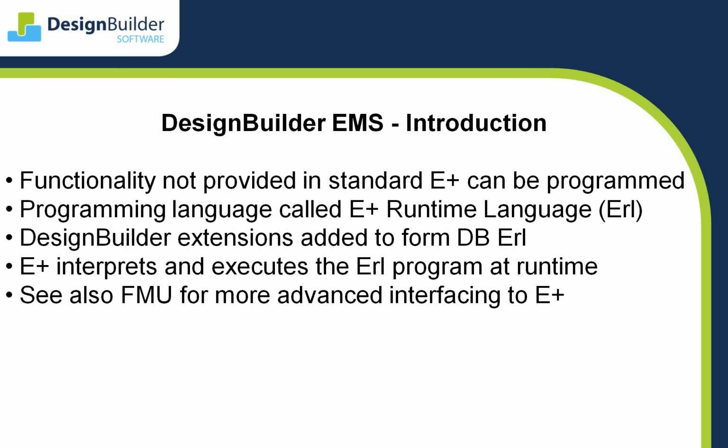The entire EMS program is contained within the IDF file generated by DesignBuilder, enabling you to run your simulations locally or on remote servers. EnergyPlus provides an inbuilt language called ERL, and DesignBuilder provides some significant extensions. These allow a single piece of EMS code to be used by every zone, which makes it portable between models and significantly reduces the time and effort to use the EMS.